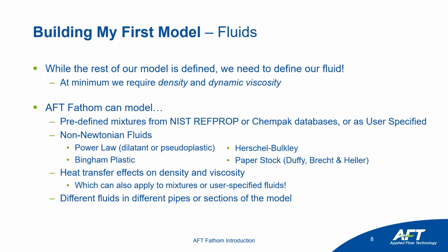One case study we had was a brine system where they were pumping brine, or I believe water, into an underground cavern, which was then returning brine. So they were able to model both segments of the system, considering things like the volume balance or mass balance across that cavern during steady state.